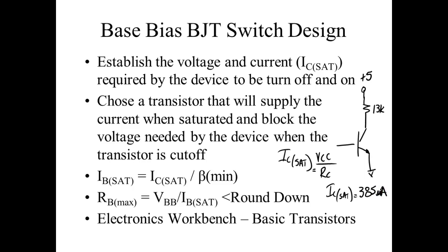Is everybody okay? Now we're using a 2N3904 to run this. This is well within its limits. It can handle up to 200 milliamps. So what am I going to do next? I'm calculating the size of this resistor right here, and that's going to be connected right there. I know this resistor is going to drop 4.3 volts, right? So what size resistor would I use over there? What beta are we going to use?